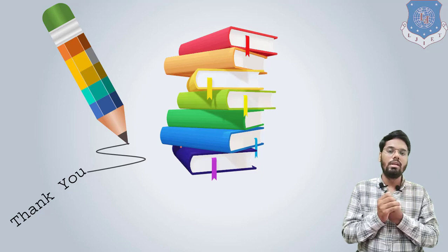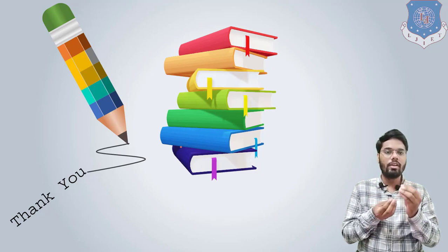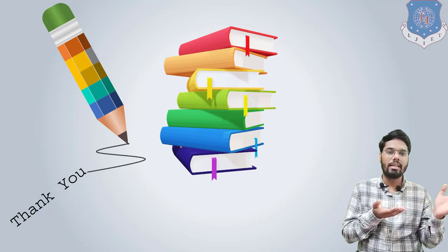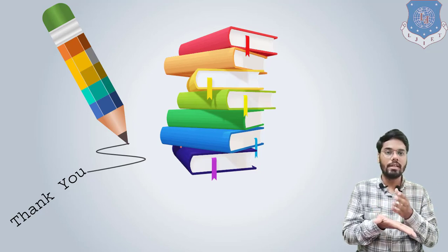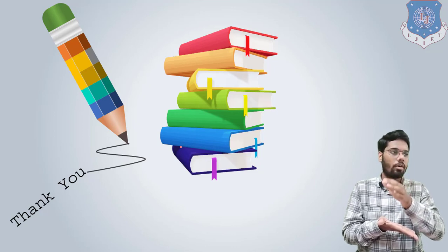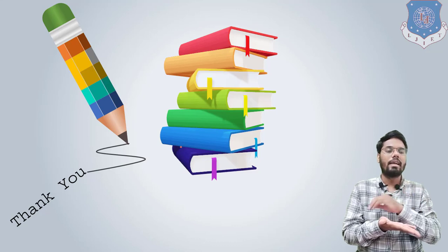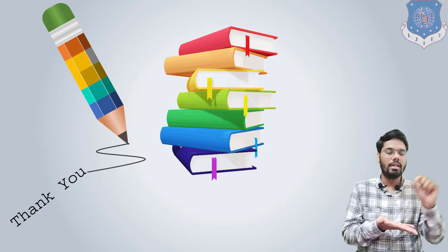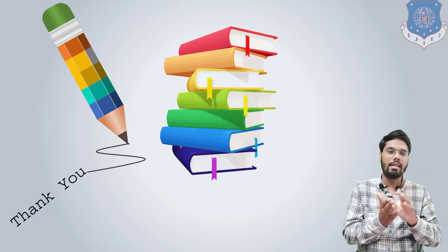We also learned the Lambert cosine law, which shows the intensity of electromagnetic waves in a particular direction. We know that for a real surface, the intensity of electromagnetic waves in the normal direction is maximum. So for directions other than normal, we just need to multiply by the cosine of the angle. For angle theta, the intensity of radiation would be I_N cos theta.